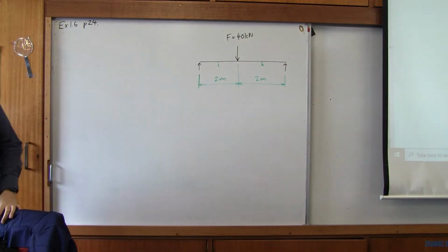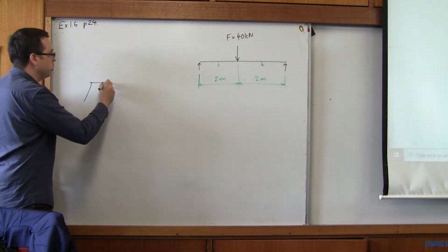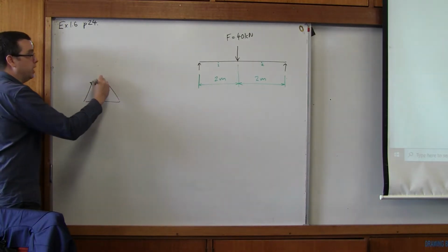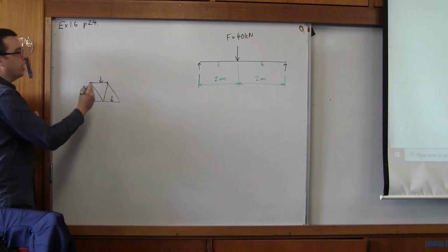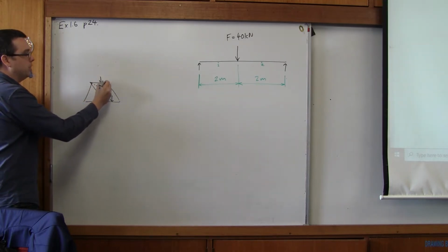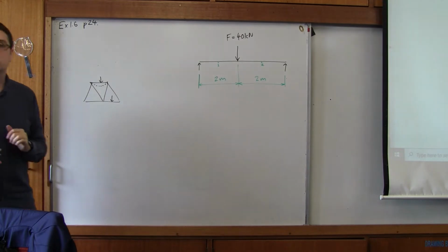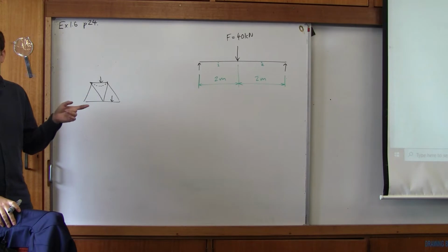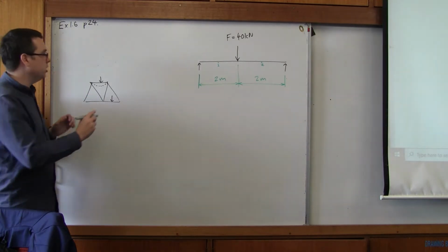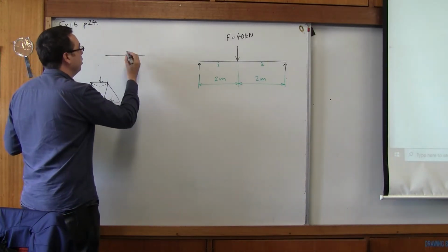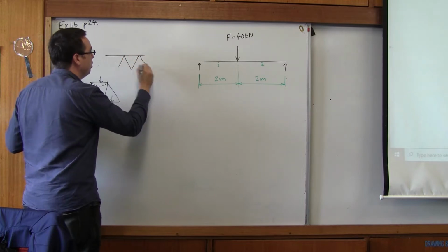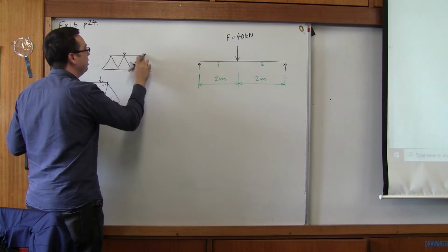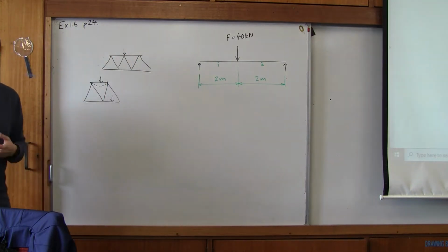The idea is that if we have our truss, I'm going to draw this really quickly, and I've talked about this in another video in much more detail. If we apply a force, say, here, or here, we will get bending and the truss will fail, because trusses are not designed to deal with bending, not if it's a significant force. So when you do your assignment, it's really important that if you're going to apply your load to the top, your truss is designed with supports at the top to support that weight.